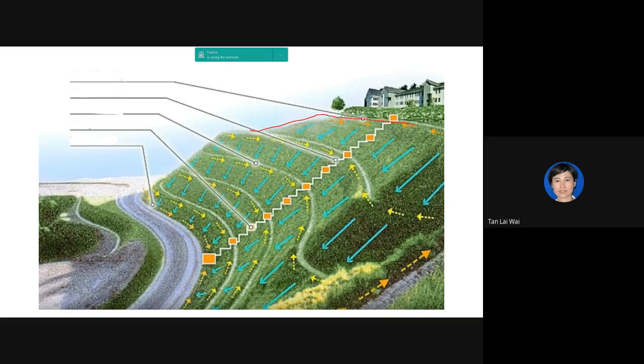This is the area that you are considering that will flow into this bench drain here. From top view, we only see the plan dimension, but in reality the area is actually larger. Do you agree with me? Yes, because of the sloping area. So for your A, depending on the cut slope, you should consider the slope to get the larger area.